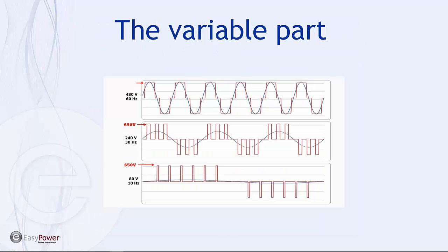The variable part is actually the control of the sine wave, and this can vary between something less than 60 cycles to something more than 60 cycles, and frequently the switching controls will be several hundred hertz, if not kilohertz. I've seen designs where you have 1,000 hertz for the switching frequency, and some that go as high as 10,000 cycles and above for the switching frequency.